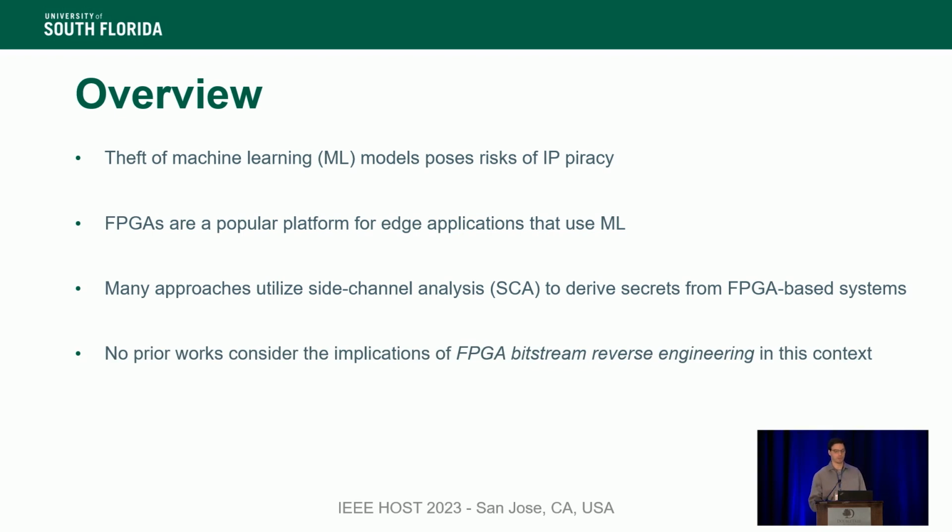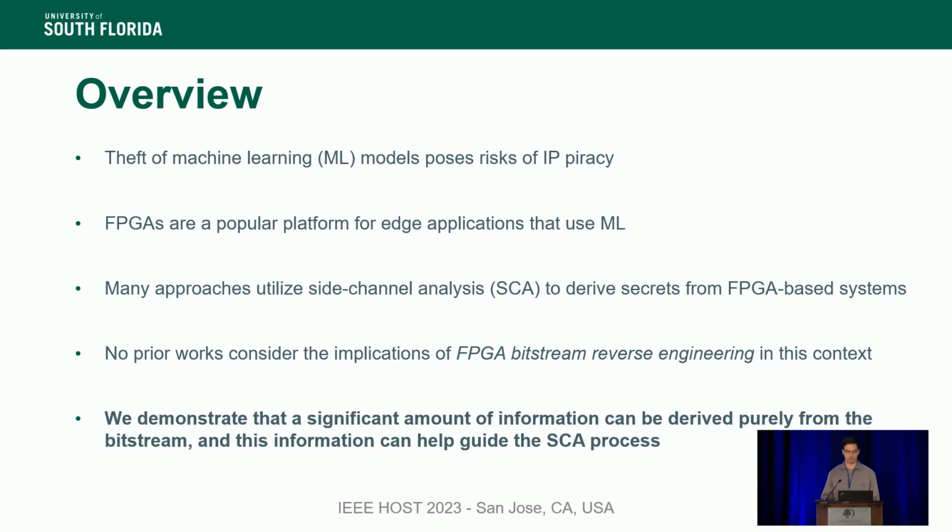And at this time, no prior works consider the implications of FPGA bitstream reverse engineering in this context. All of the current work has been focusing on side-channel leakages. So in this work, we demonstrate that a significant amount of information can be derived purely from the bitstream, and that this information can help guide the side-channel analysis process.